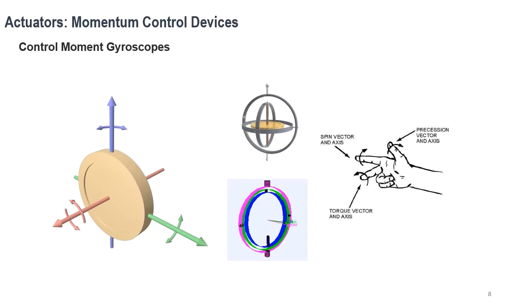A control moment gyro, or CMG, system is a torque source for 3-axis attitude control of an artificial satellite. A CMG consists of a flywheel rotating at a constant speed, 1 or 2 supporting gimbals, and motors which drive the gimbals. A rotating flywheel possesses angular momentum with a constant vector length, and a gimbal motion will change the direction of this vector and thus generate a gyro effect torque.